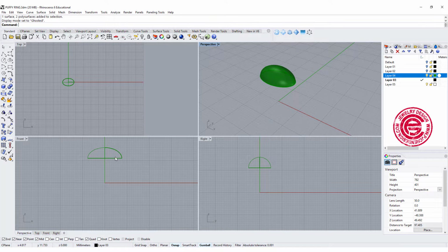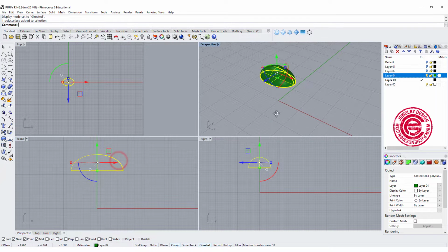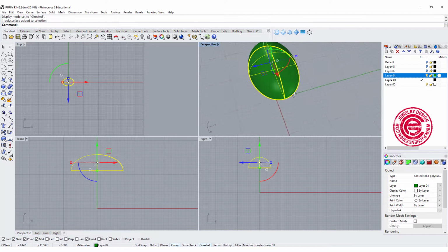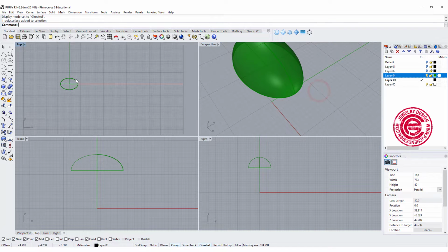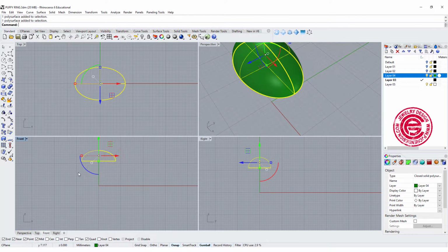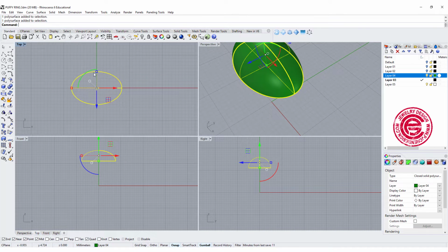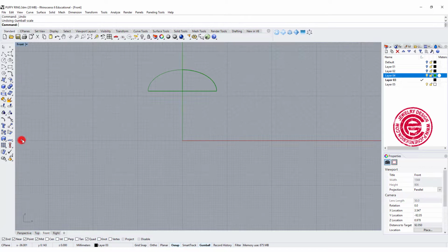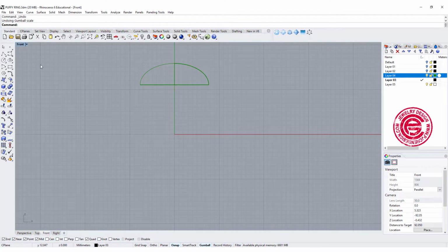First of all, we are going to create a cabochon stone, for whatever that size is. Since I don't have a size, I'm just gonna make it up for whatever looks good for this design. What you can do is make a sphere, cut it in half, and scale it in one direction to make it into the size that you want. Then we go to the front view, and we need to draw a profile for it.